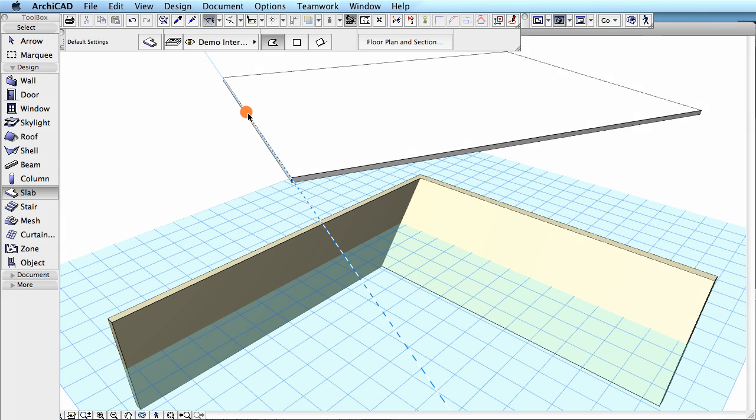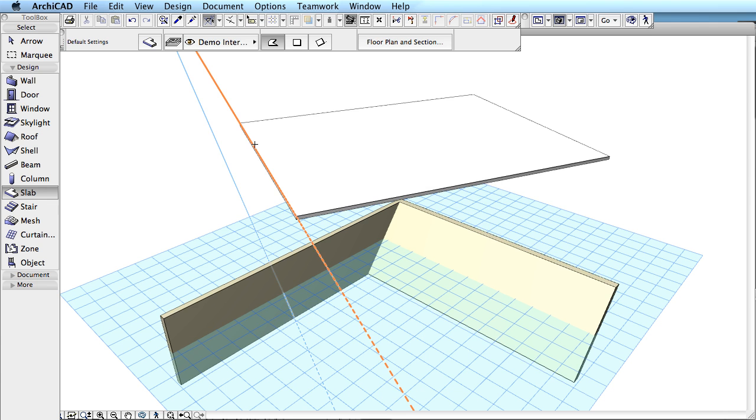We can hold on to this 3D guideline by clicking the orange dot. We can freely create and reposition guidelines in 3D views. Please also notice that the projection of the activated guideline instantly appears on the editing plane below, represented by light blue. This greatly helps all 3D element creation and editing.